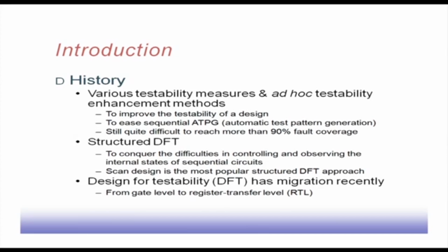Another issue was sequential ATPG. If my circuit has sequential elements like flip flops, then some sequential ATPG algorithms came up that can generate test patterns for sequential circuits, but still getting more than 90% fault coverage was difficult, because of the same reason that many of the points may not be accessible.